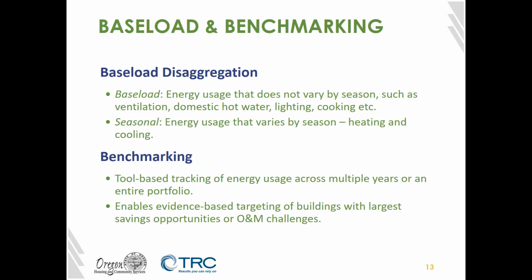So baseload disaggregation means separating your baseload energy usage from your seasonal energy usage. Baseload is energy usage that does not vary by season, such as ventilation, domestic hot water, lighting, and cooking. To be totally accurate, domestic hot water does vary slightly by season. People take slightly longer, slightly hotter showers in the winter than they do in the summer, but people use hot water year-round. Lighting, it's darker in the winter, and so people have to turn on the lights slightly more, but it's not significant. Cooking is pretty constant year-round, except for a spike around the holidays. But for the most part, baseload is the energy that is constant.